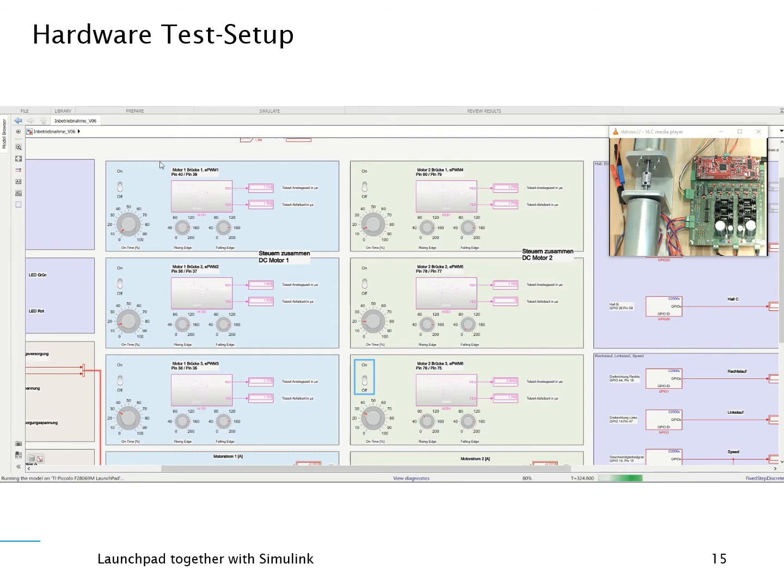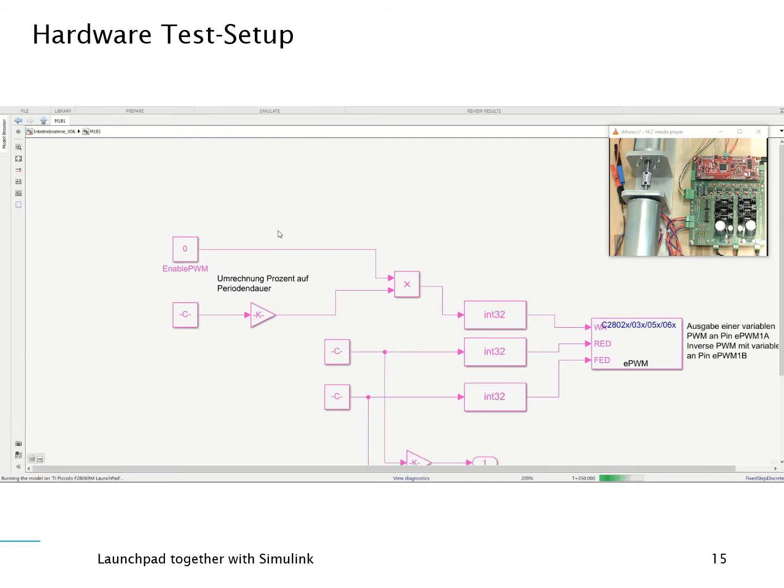And within this block, I can turn the half bridge on and off with the value. Then with the PWM value, I program this way. I can set 0 to 100%. Then I can change the rise time and fall time of the dead time counter within this PWM block. Now let's have a look inside this PWM block.